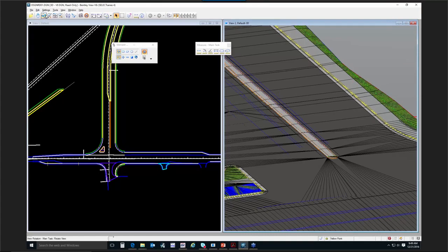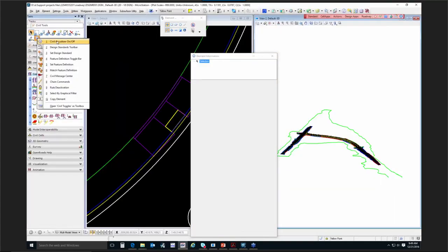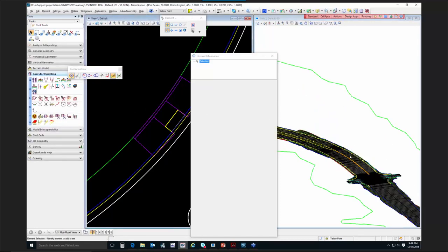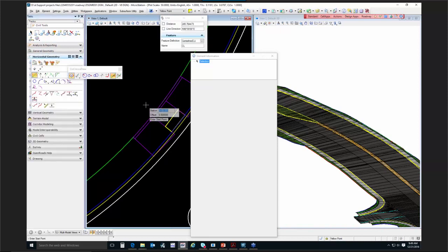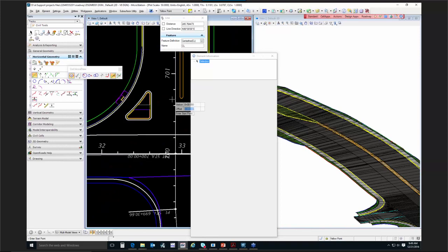So the way that you can check slopes in a model that's delivered is there are tools within Open Roads where you can just simply measure with Civil AccuDraw. If you turn on Civil AccuDraw and you're looking at, for example, station offset, if you click in this view here, it doesn't give you specifically the slope, but you can get XYZ just by placing a point or doing an analysis between 2 points. So for example, if I wanted to place a line, it's tracking station offset, and if I just set the baseline